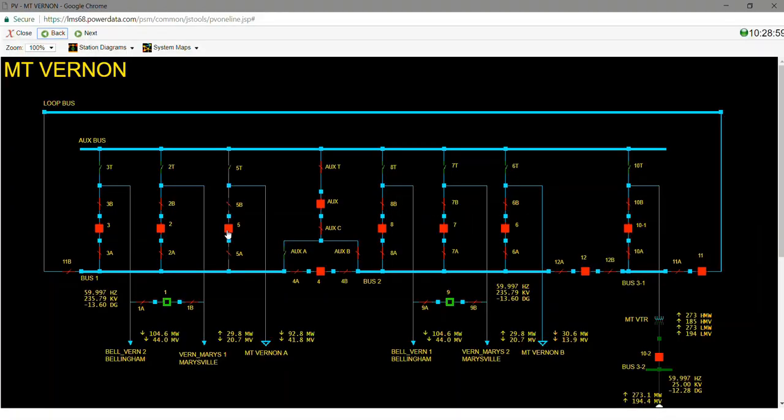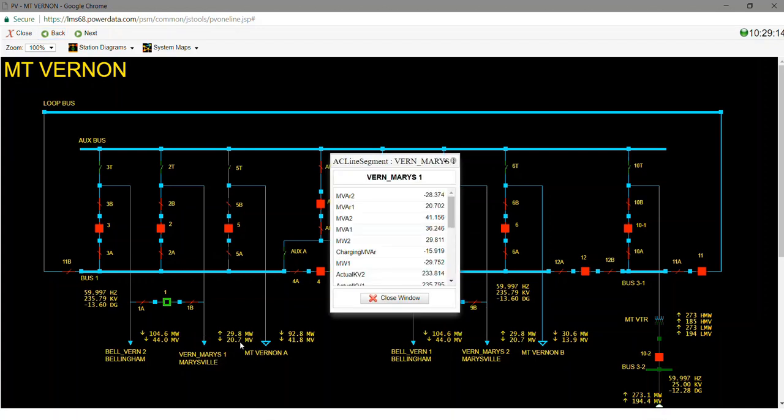In Power Simulator, anytime you want to use a device to operate or navigate, like we just did by clicking on that, we just gave this a left click. Anytime you want information about a piece of equipment, you can right click and select Device Info. So a left click is basically your operational function, and a right click is your informational function.